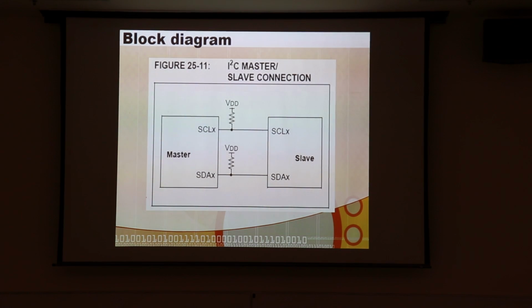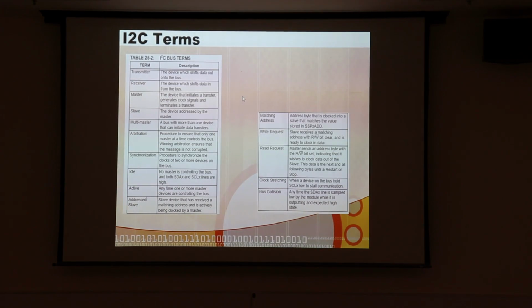It's got one slave address. The other package is a ROM, and it's got another address, and you can store maybe 128 bytes in this ROM if you want, or maybe it's 256. And so you can store some non-volatile information there if you want, like maybe an alarm setting or something like that.